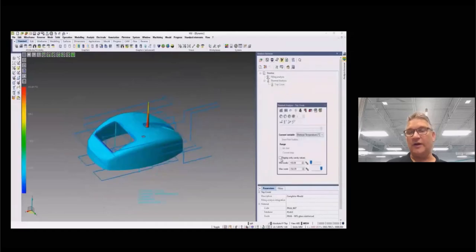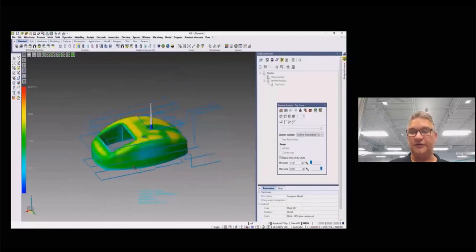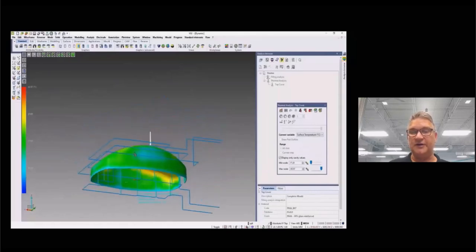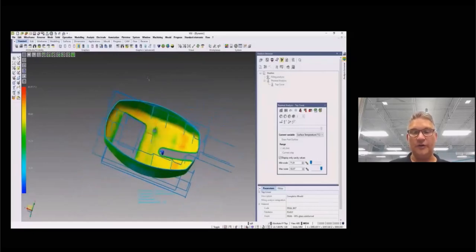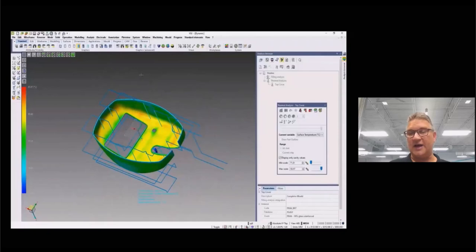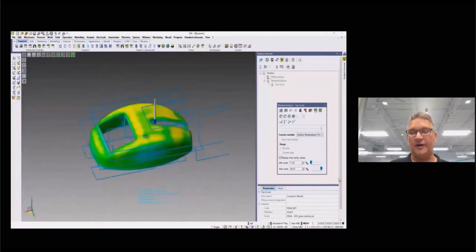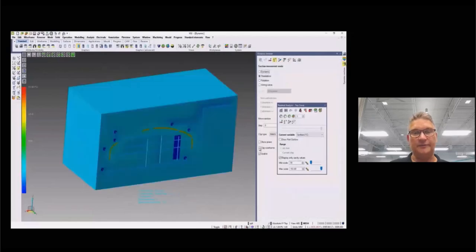So now we're ready to visualize the results, reviewing the temperature of the plastic material at the end of the fill with the solid fraction variable. It is important to know the part can be removed. Equally interesting is the distribution of the surface temperature of the mold, which in this case, there are some visual differences between the cavity and core part of the mold. Remember that such non-uniformities can lead to the deformations of the part. Therefore, optimization is very important.